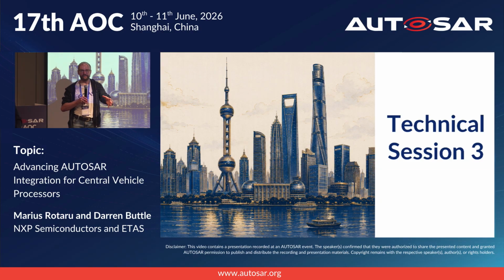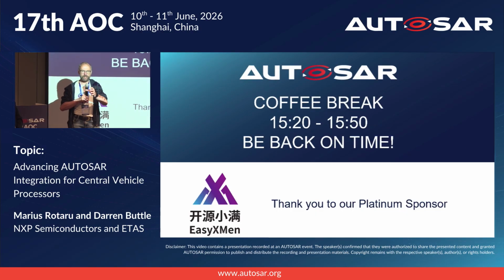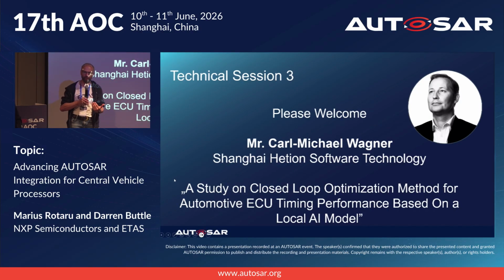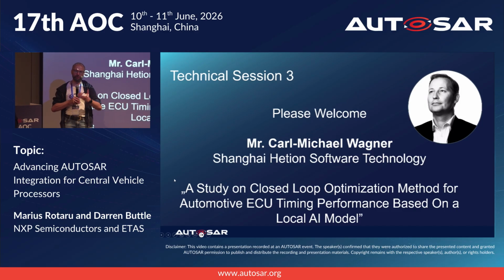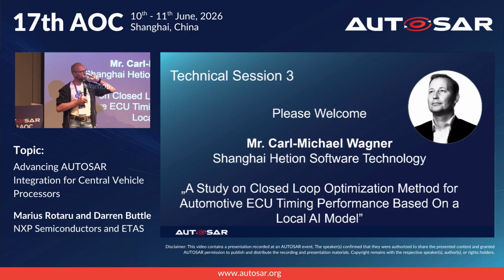But if we went for something like, let's pick an S32K5, for example, whole bunch of R52 cores on there, some really nice hardware virtualization, but it's a lot less rich in core features, and we're seeing people come up with applications where, okay, I want to create 3 or 4 partitions, and then a partition with 2 or 3 cores in it, but then I want to virtualize 7 or 8 virtual ECUs onto that. And in that case, for that cohort, you're running a hypervisor on that. But there's nothing in this case to stop us running a hypervisor on one of those cohorts to provide CPU core virtualization above, to create a set of virtual cores on that.